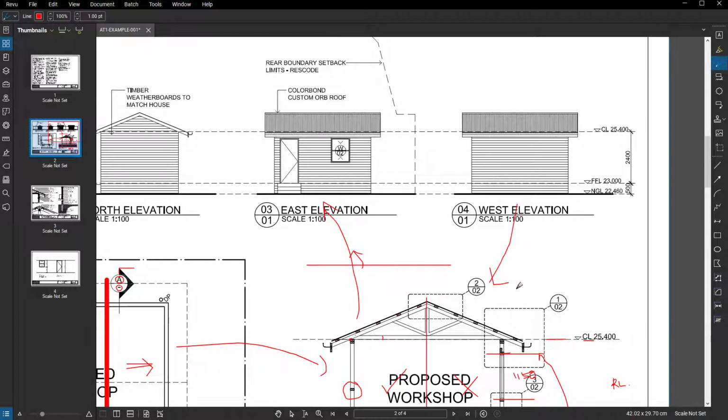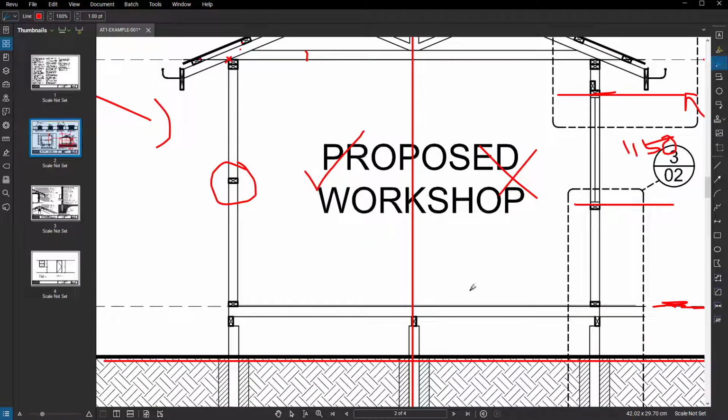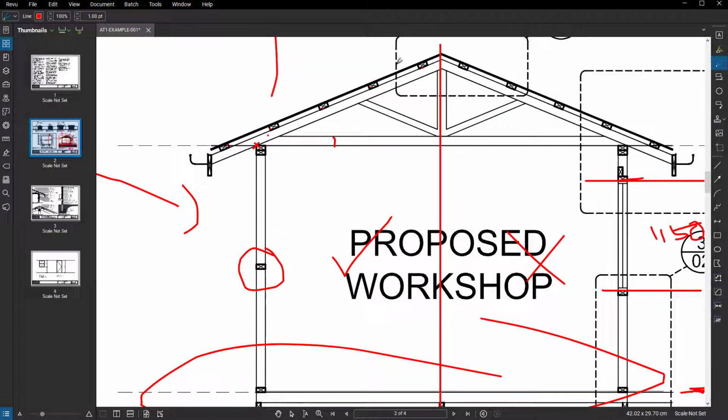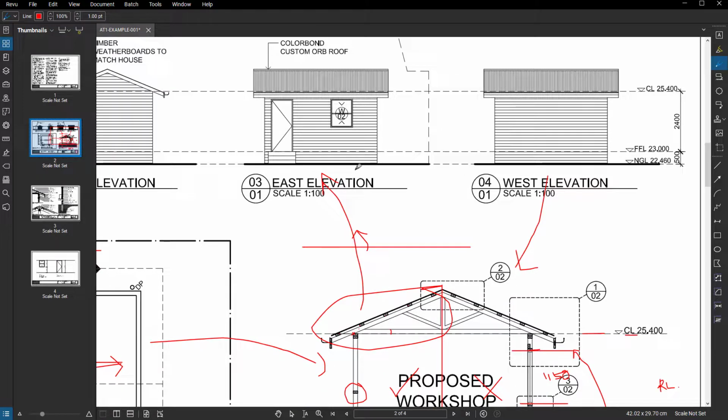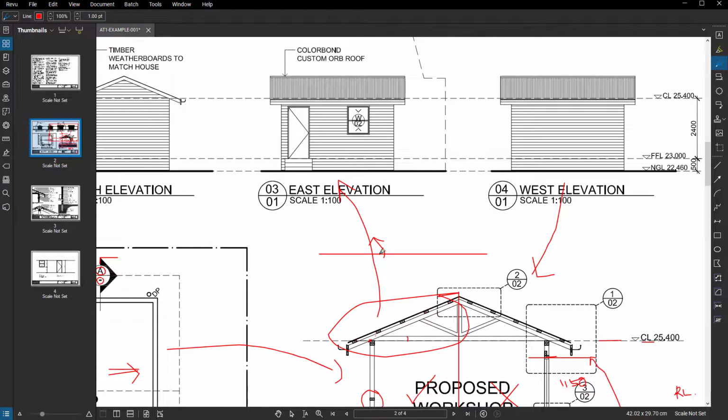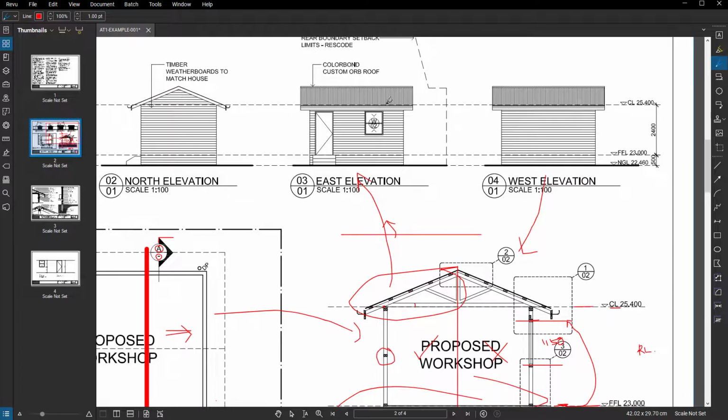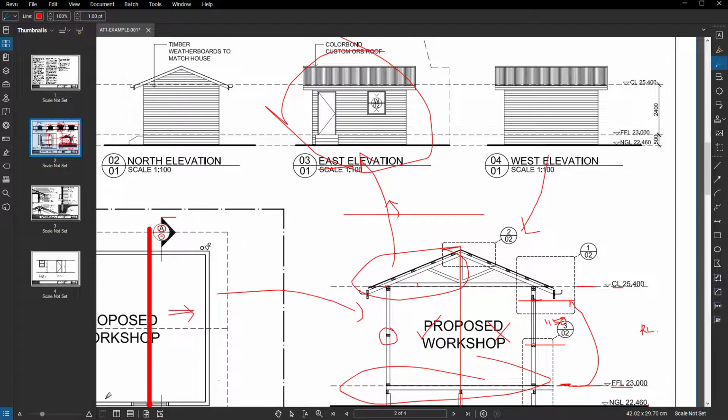Now, you can always design a building with a facade in mind, and you can sketch facades, and that's extremely common. But when it comes to actually documenting those buildings, those projects, you really need to firstly ascertain, what is your subfloor structure, what does your roof structure look like, because that will then tell you about, what is your building envelope zone and how you're going to clad that. So the first elevation we'll start with will be what specifies the east elevation or the front elevation.